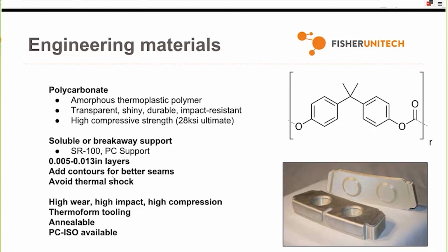And that is kind of important because the soluble support tank can actually cause some problems with polycarbonate. First of all, PC is susceptible to thermal shock. So it's a bad idea to take a hot part right out of the build oven and then toss it right into a cold bath, or even vice versa, a cold part into a hot bath.